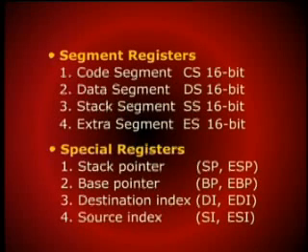The segment registers, each of 16 bits, are the code segment, the data segment, the stack segment, and the extra segment. Through these segments, we have a possibility of relocation, and the code could be made really relocatable in a way the programmer would like. Similarly, the stack pointer could be used for implementation of stack, and the base pointer for the base index addressing mode, and so the other registers.